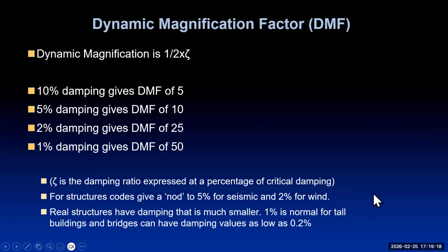The code, this is the interesting thing, and this is where there's a rub with designers in that they know that in the design process, they can estimate what damping is. And they're allowed to use 5% damping, 5% of critical, in the design process. Now, that being said, what we're talking about is measuring it at lower amplitude. And when it does get to higher amplitude, because of all this modal coupling and things, 5% damping is probably a conservative number for what you would achieve during a high amplitude event.